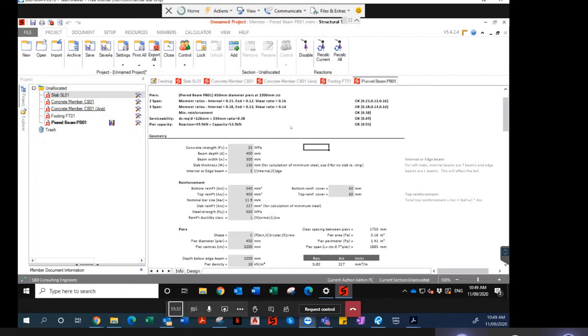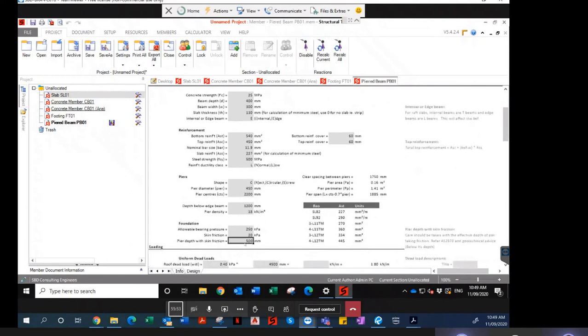So that's the most critical. If we are founding just at 250 kPa and we're not going into the clay, it doesn't help us. But most of the time, they would recommend about a meter into clay to achieve that 250 kPa, isn't it? Because on the clay, it's usually one. Make sense?